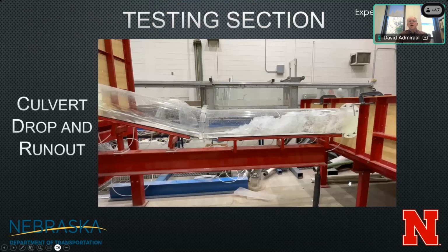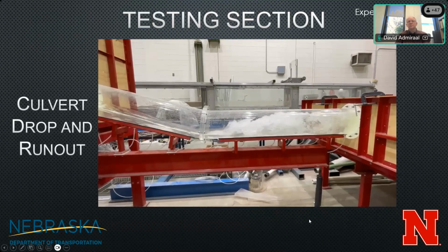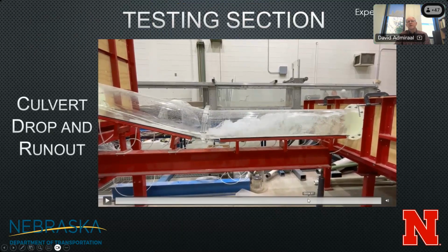So here's a side view to show you what it's like in the runout section. And so I'm going to run the video here. So you can see that there's a big hydraulic jump right here inside of this culvert. And in a flow without a tailwater, you wouldn't see this here. So what's happening is we have backed up the flow in this tailwater tank enough that we get a hydraulic jump in here.